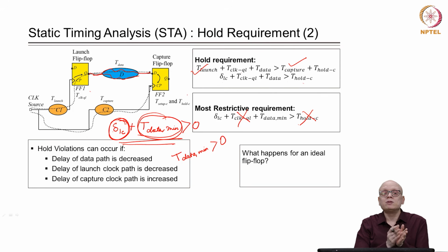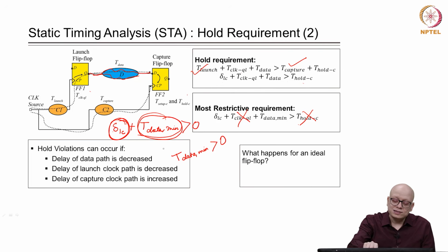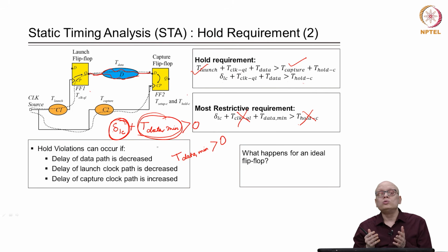The corner cases will be the situation in which we have a kind of shift register, in which we have a flip flop and then another flip flop, and there is no logic between them. If there is such a scenario in our design, then the hold violation is more likely to happen in those situations. Another thing that we should infer is that during the logic synthesis step, it is typically not that important to look into the hold check.